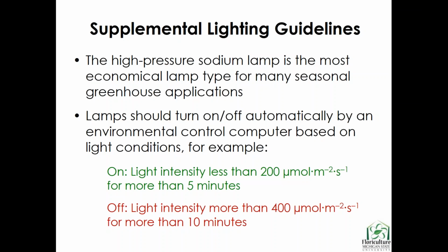So in terms of supplemental lighting guidelines, currently the high pressure sodium lamps are still the most economical lamp type for seasonal applications. So meaning if you're only using them for young plant production. Now, LEDs obviously have their benefits, especially if you're going to be able to utilize them year round.